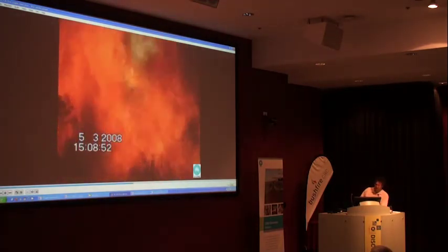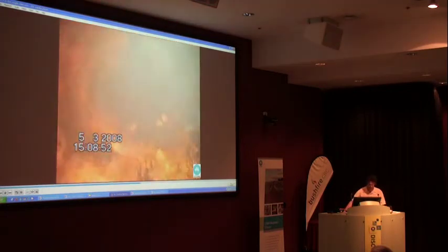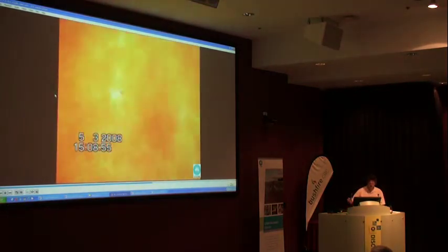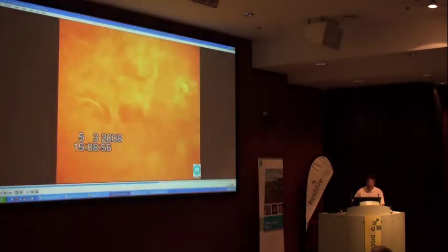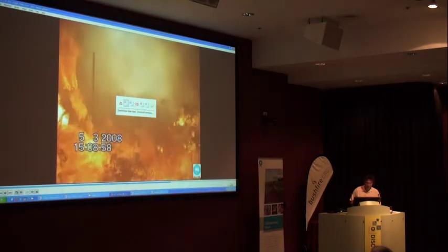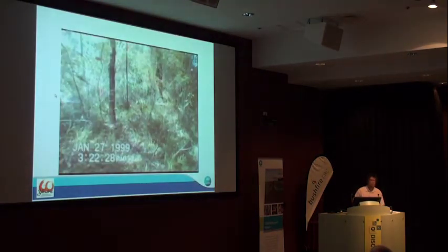It's a totally different mechanism, as you see in these two fires. In the previous fire, at the flame front, we didn't see the flame front approaching, but as the flame front was approaching, the fuels were really being cooled by the air, whereas in the other fire, we could see that convective transfer, or advection, was impacting the fuels much earlier.